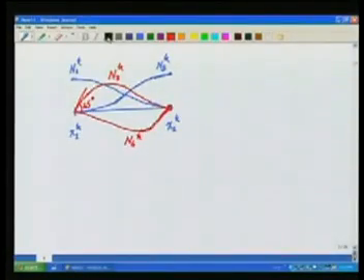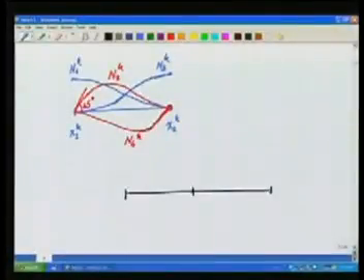A simple question is, what are then the global basis functions? Because remember, as far as the approximation is concerned, we are creating these global basis functions which are C1 functions, and the pieces of these global basis functions are these shape functions in the element. So let me draw 2 of these representative functions.